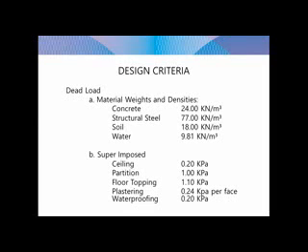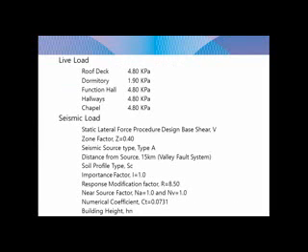Under the live load, we have the roof deck, for which we use 4.8 kilopascals. Same with the function hall, hallways, and chapel. While for the dormitory, we use 1.9 kilopascals.